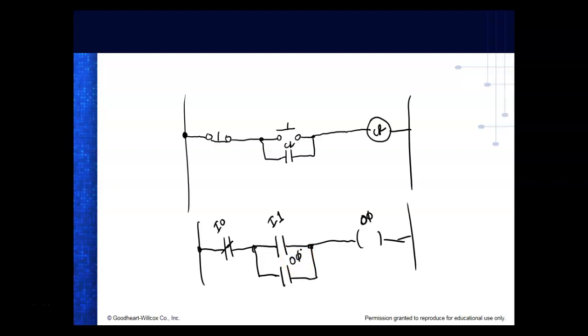Now that's the normal tendency for us to do. We're going to have a problem with this. So if I'm going to wire this up, here's my PLC. We'll have our common, and I'd run this down here. And I would come up here and use a normally closed push button, hook it up to input 0. Then I'd come down here and have a normally open push button, and I would hook this up to input 1. On my output side, we're not having problems. We're having problems with input.